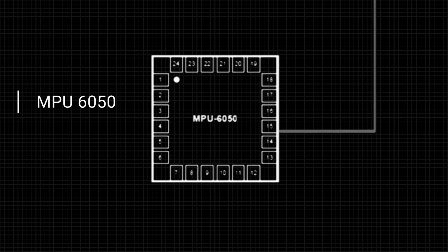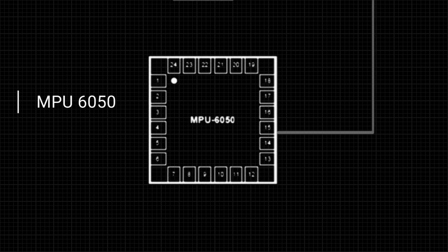For tilt sensing, we employ the MPU 6050 sensor board, which features three accelerometers aligned with the X, Y, and Z axes. These accelerometers feed their output into three analog-to-digital converters (ADCs), each with a 16-bit resolution, converting the data to digital values. These values are stored in six 8-bit registers accessible to the Arduino via a serial interface.